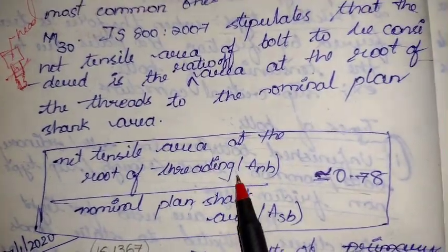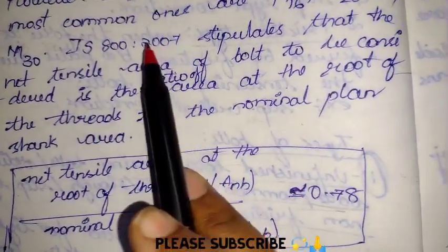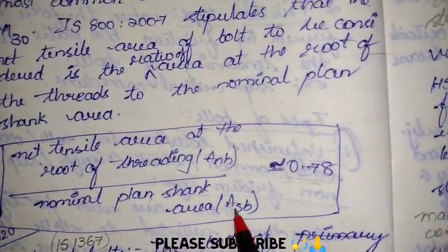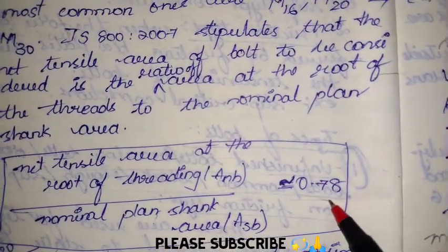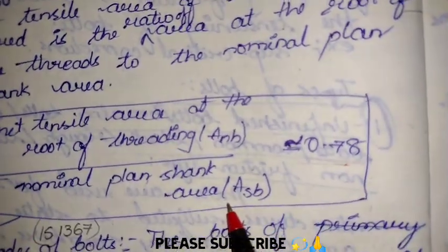So the ratio of the threaded area to the shank area is 0.78. This is as per IS 800. Okay, A_nb divided by A_sb is 0.78. This is the threading area and this is the shank area.